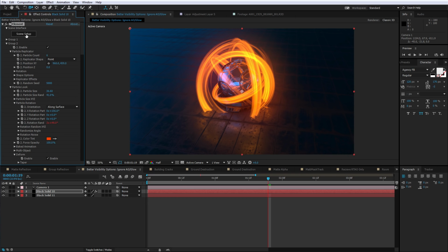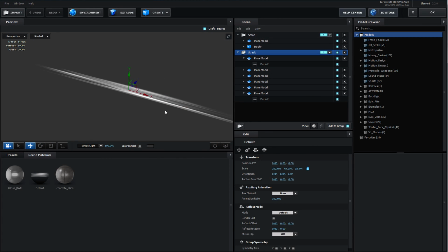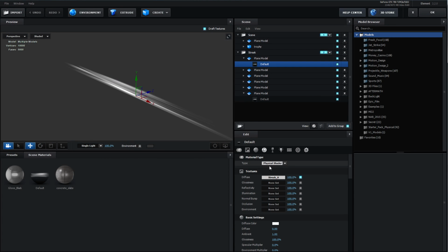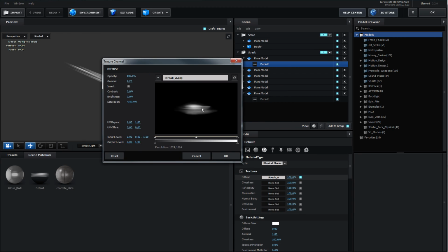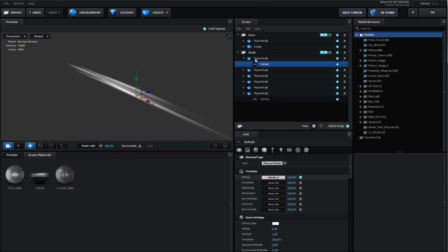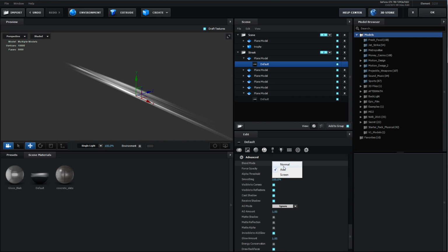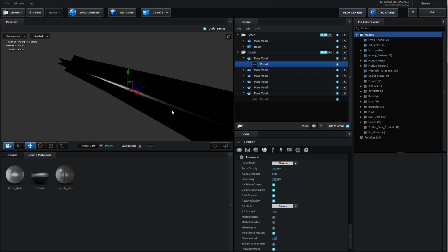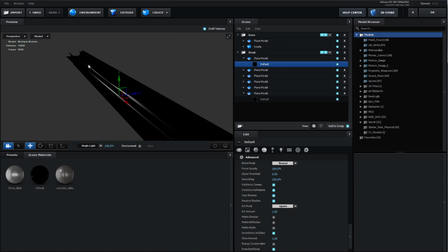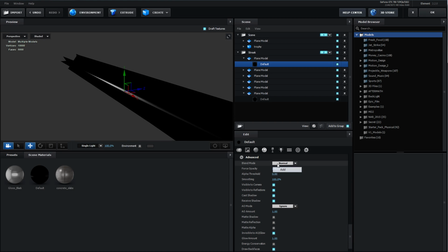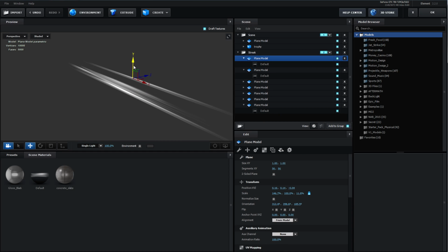And basically, if I go into our scene setup, I created a streak using a simple texture. Looks just like that. And I've set that material to be an additive material. So if I set it to normal, you can basically see it's just a plane that's stretched out. And we set it to add, and I made a few copies. Hold down Alt, rotated a few copies, stretched it out, all that kind of stuff, right?